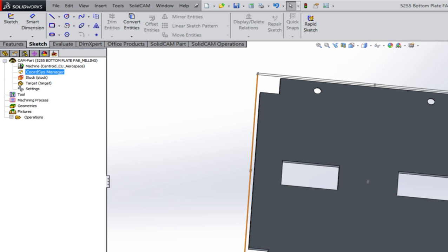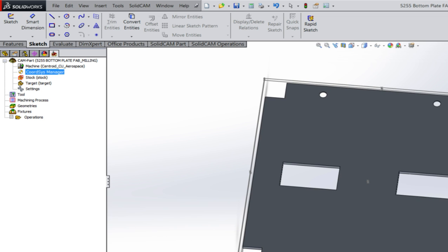What would be a way to mitigate that? Make the stock bigger. If you don't trust yourself and you're not going to take care in doing this, instead of a 1/16 of an inch, maybe you could cut it 1/8 of an inch bigger here, or a 1/4 inch. Now don't get crazy, then you're just wasting material and costing time, but maybe you want to cut this a little bit bigger and make sure, absolutely sure, that you're going to get this piece out of there. Okay? Cool.